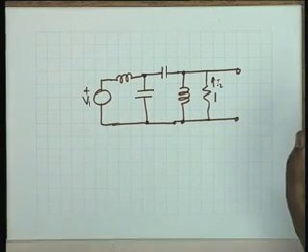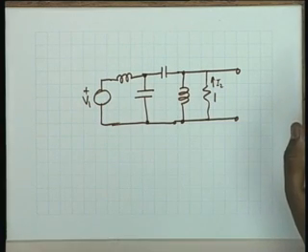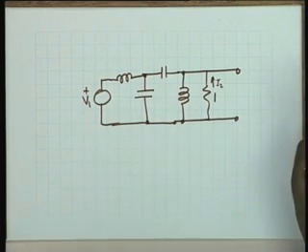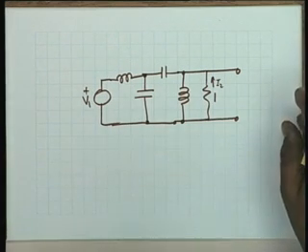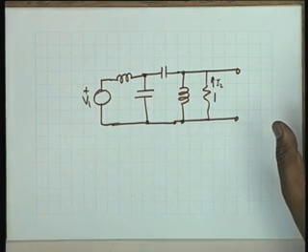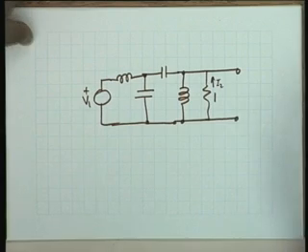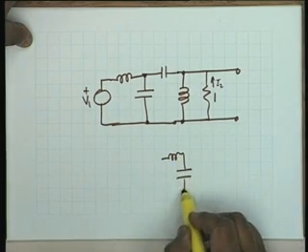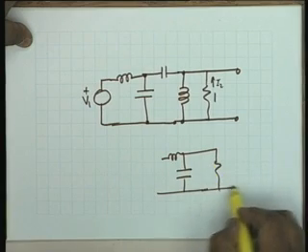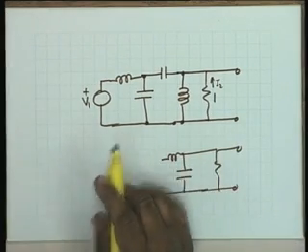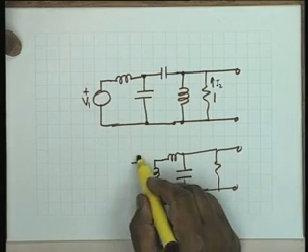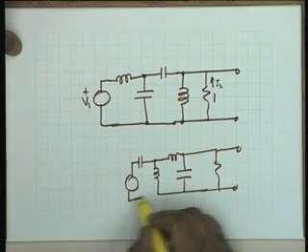Okay. So why do we take these transmission zeros in the order of transmission zeros at origin and then at infinity? Good question. Why did you want me to take the infinity first? Yes, we could do that. So we could have done this like this. This is also perfectly valid. The element values shall be different. Then I should have an inductance and a capacitor. This is perfectly all right.